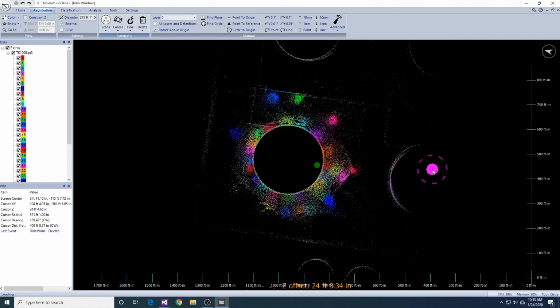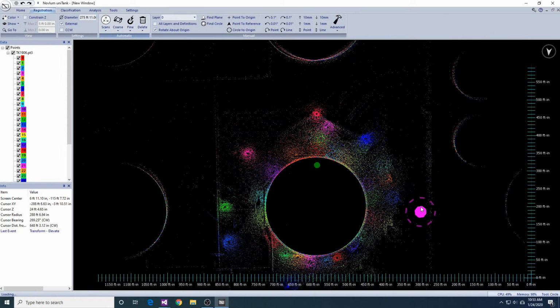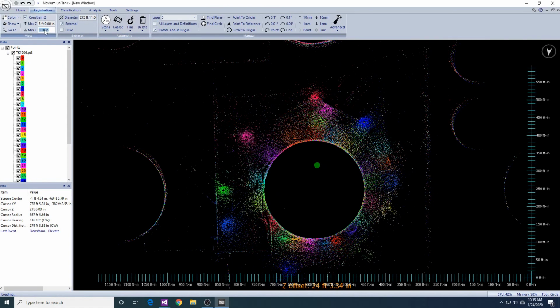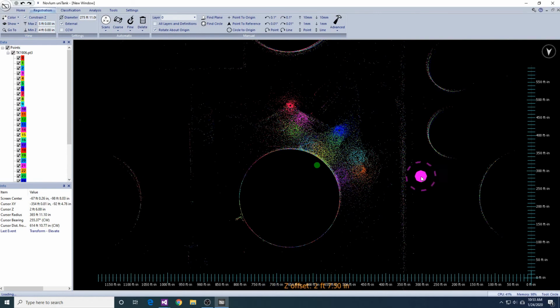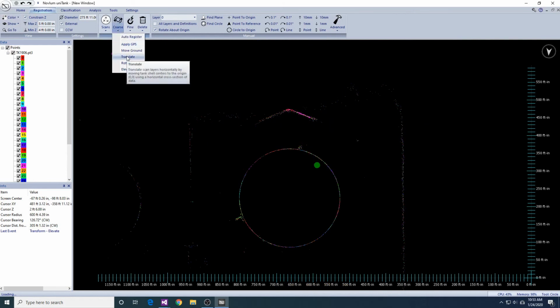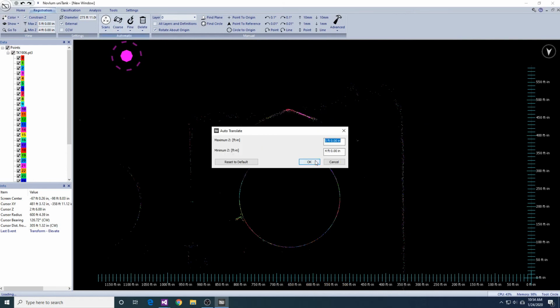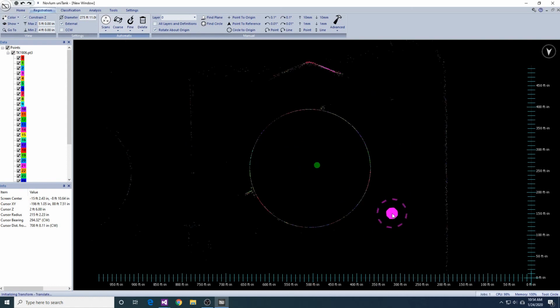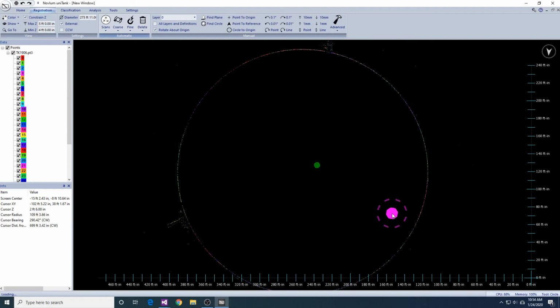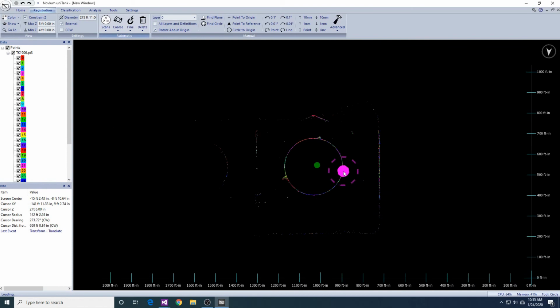So for external coarse registration, it is important to refine the coarse registration. What we do is we run Translate, Rotate, and Elevate separately with the Refine option. When doing Refine Translate, we want to put our best estimate of the tank diameter if we know it. With external scans, the diameter estimation from a single scan is not always accurate depending on the coverage area of each scan. Next, we want to do a refine rotation using a horizontal cross-section with as much asymmetry as possible.